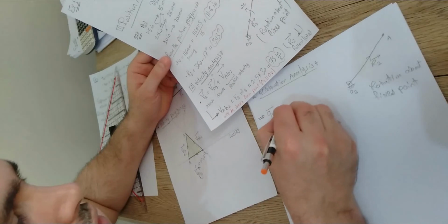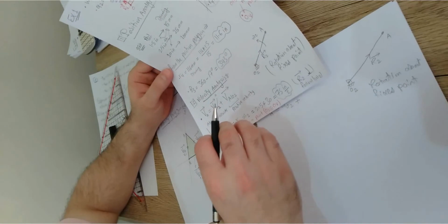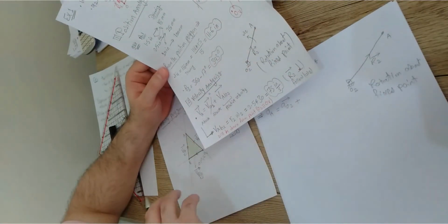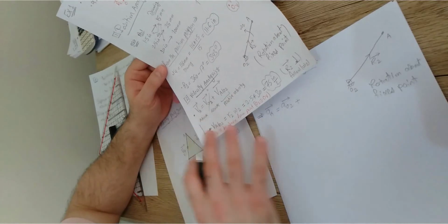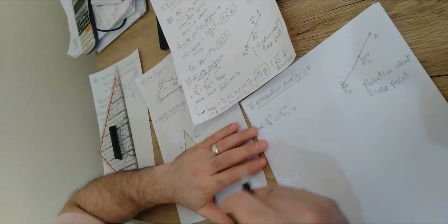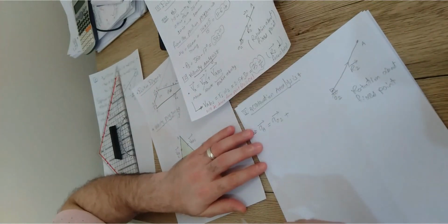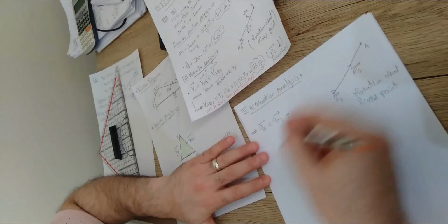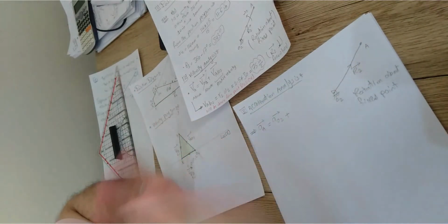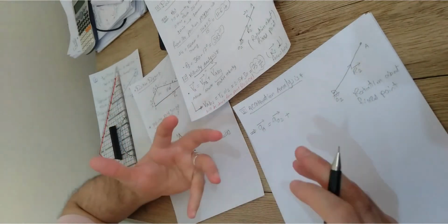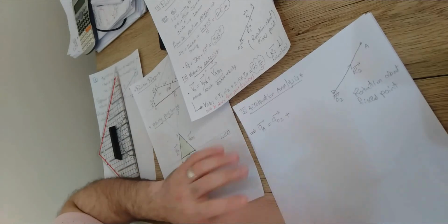It should equal the acceleration of O2 as a vector plus some relative accelerations. The relative acceleration is the thing that we are going to draw in the acceleration diagram, or the acceleration polygon, as we did for the velocity analysis. Make sense? But if you remember from the dynamics class, and from the complex algebraic method that we already covered in this course, a length that rotates, whether about a fixed point or with no fixed point, meaning general motion, will have two components of the acceleration. One is normal and the second one is tangential.